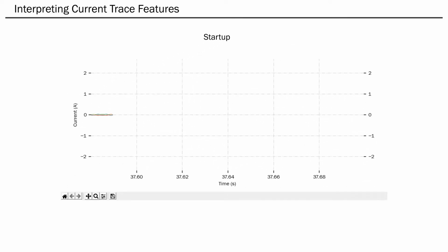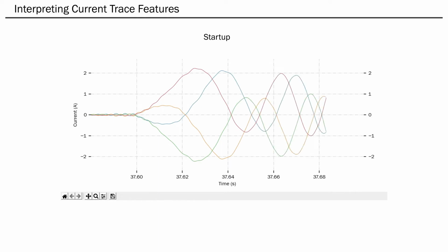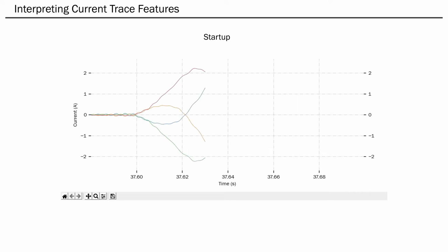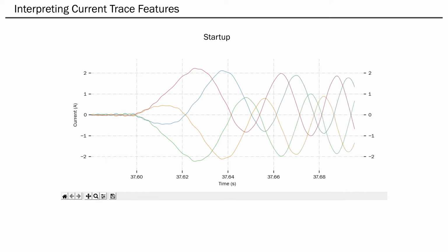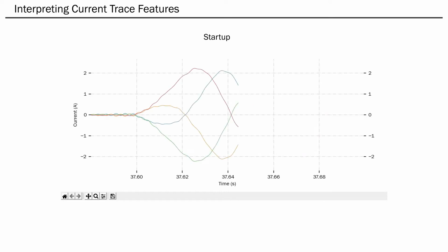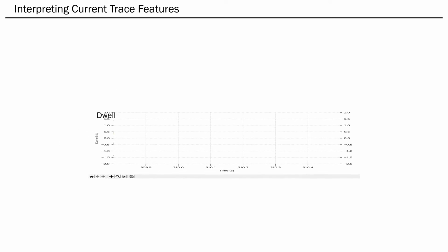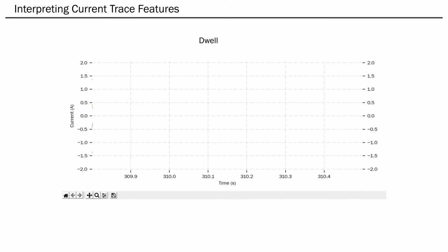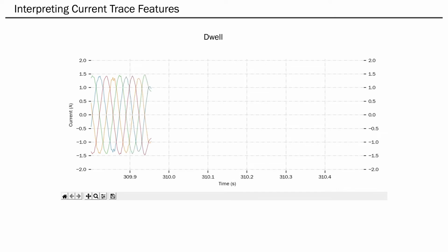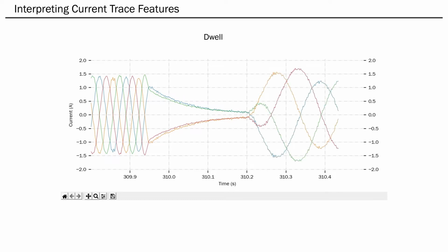This is what the current looks like when the motor begins moving from a dead stop. Note that the phases are not peaking at the same level. They have different DC offsets, which converge to an offset of 0 over time. This complicates automated recognition of the peaks. We have to detect them relative to the prior and following current values. Something similar happens when the motors come to a full stop. The current reaches its peak and then gradually trails off, approaching 0. When it starts back up, we see 1 or more peaks worth of unequal DC offsets once again.